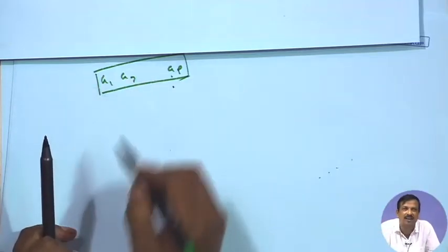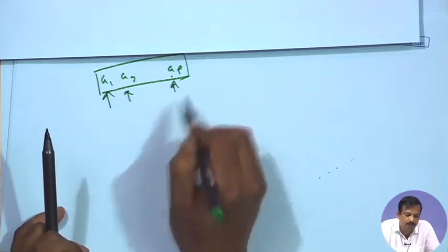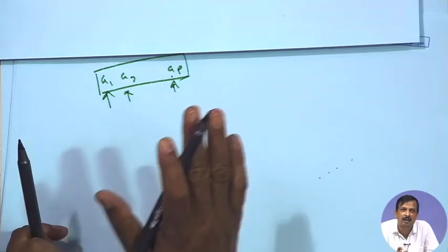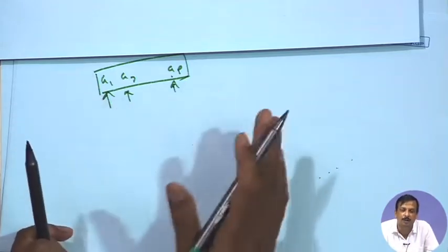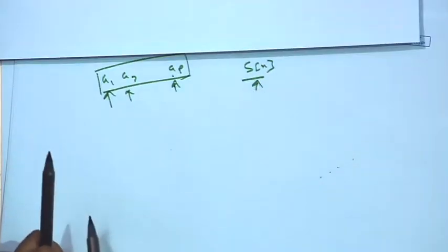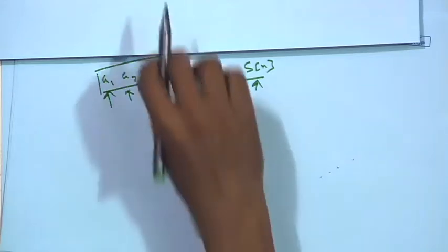So, this is nothing but a filter, and those are the coefficients of the filter. If I design an all-pole filter using these coefficients and pass the previous p number of samples, then the present speech signal can be predicted. So, this is called linear prediction.